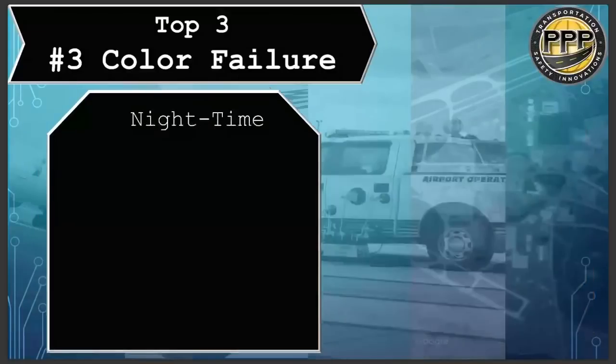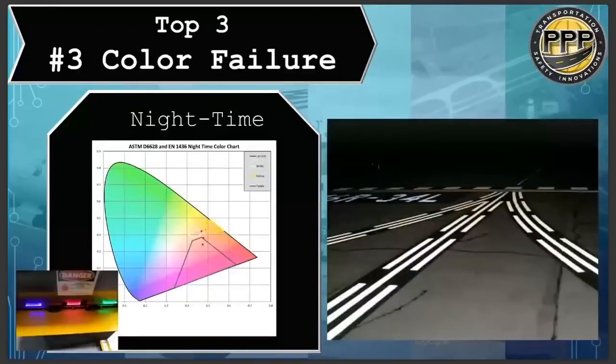on the airfield. Nighttime, particularly when we apply these markings, this is actually a great looking marking on the right side with respect to the pattern and how well it was applied. I will say that I'm going to guess, just based on the way that yellow looks, it looks almost white. And so, once again, I'd bet that the glass beads were sitting a little high in the paint.